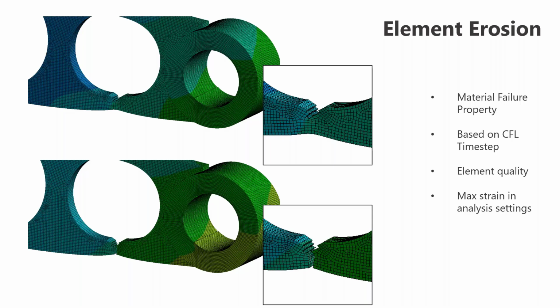It's been pointed out to me before that implicit methods also allow you to do this at some level, where you can set the death of an element based on certain criteria. It's really baked into the explicit software in a way that makes it much easier to leverage, though. So if you want to simulate breakage or any sort of gross failure, it can be really, really useful.